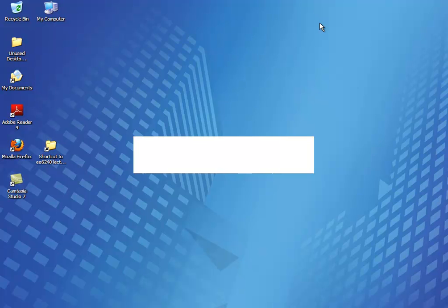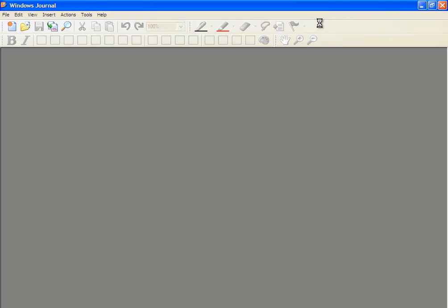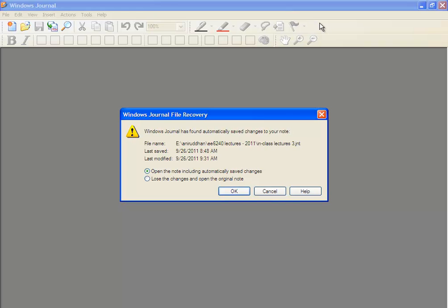So what happens is, if you look at the signal coming in at the output of the mixer, that is what goes into your baseband. You have some baseband amplification, and then you have some filtering and so on. The signal going in there will probably be a few hundred microvolts.